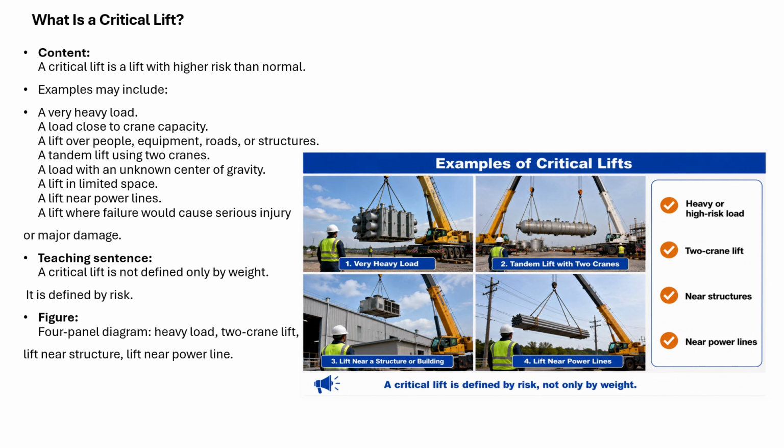What is a critical lift? A critical lift is a lift with a higher risk than normal. Examples may include a very heavy load, a load close to the crane capacity, a lift over people, equipment, roads, or structures. A tandem lift uses two cranes.